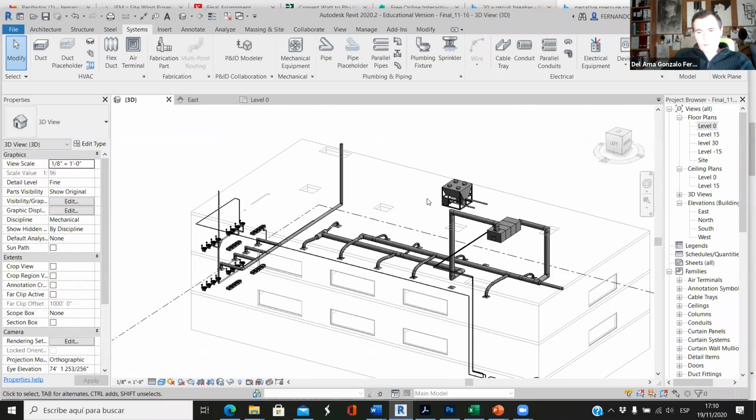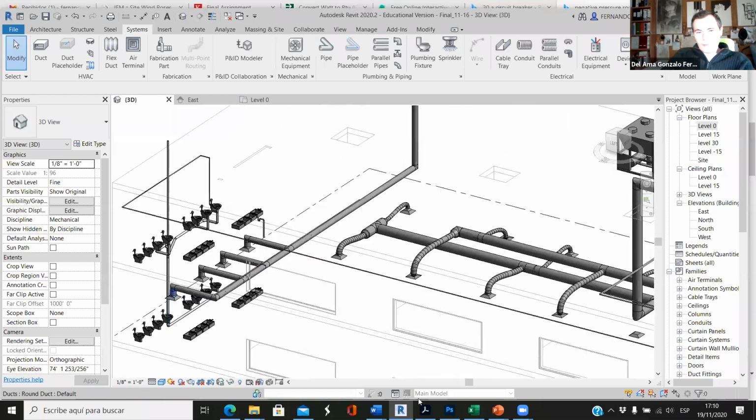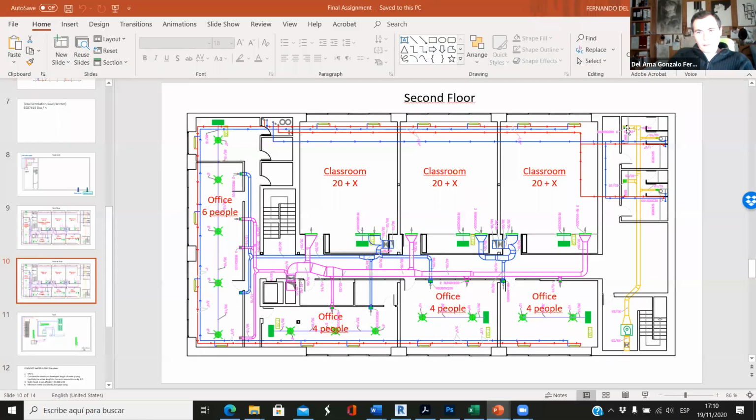Okay, so this is what I wanted to explain today. We need this exhaust ductwork coming from the toilets, and this is for every public building, or even in residential buildings. We don't have an air supply in the toilet or in the restroom. We need to get rid of the air here, and then there will be negative pressure here. So if this pressure is lower than the pressure of the rest of the building, the air of the building will end up entering the toilet. This is acceptable. What is not acceptable is that the restroom air goes out, and no, we don't want that.